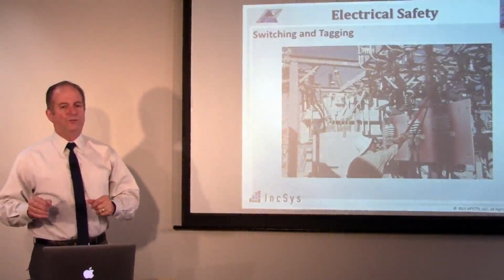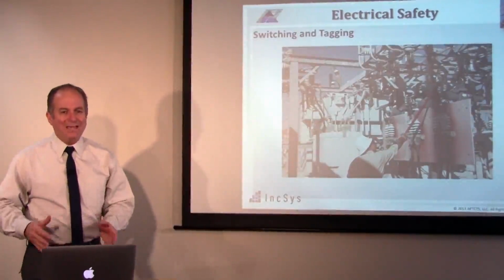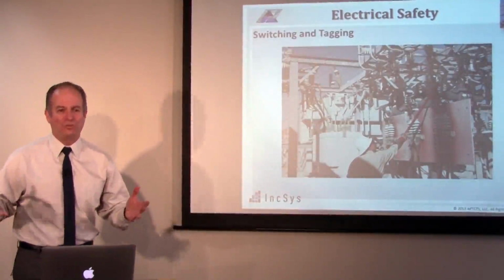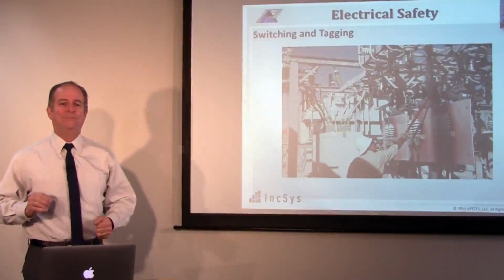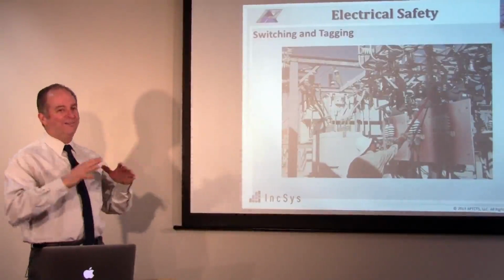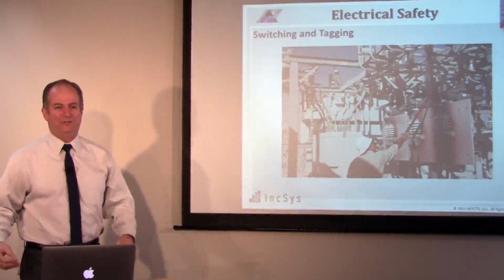But if you were to do some major maintenance in a substation, those switching orders could be pages long, and it could take hours to totally get the situation ready for someone to even go in and work on a piece of equipment. It's all about switching and tagging, and this is just a quick, high-level overview of what that is and what that means.